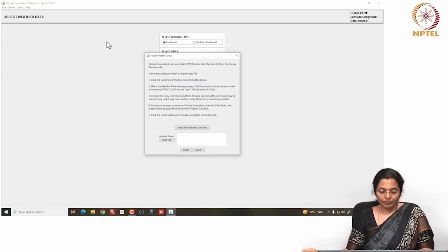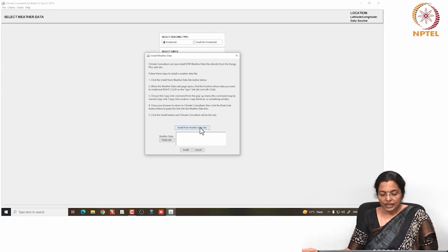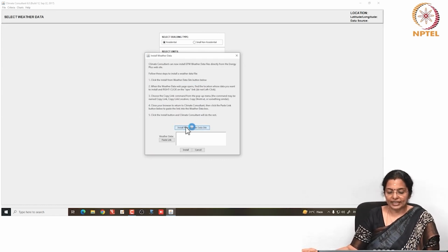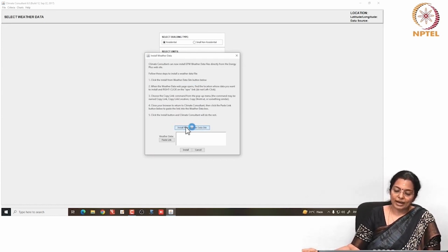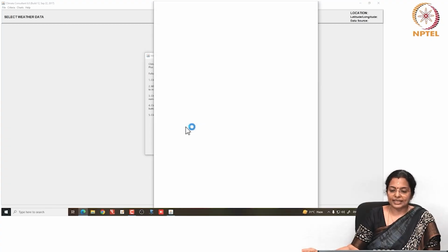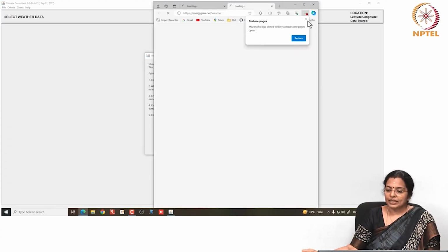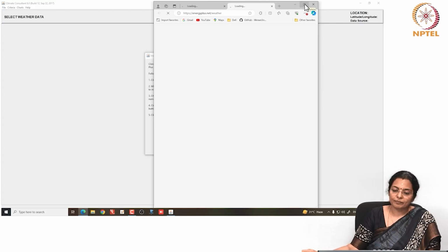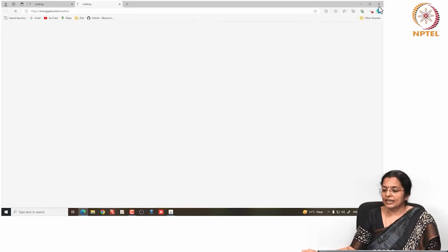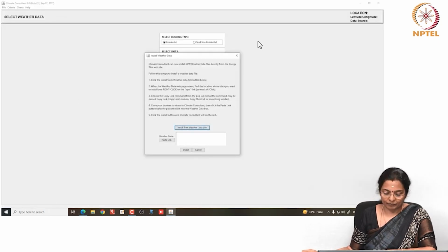Now, what I should do? I should go to install from weather data site. So, I will go to install from weather data site and it takes me directly to the energyplus.net weather station library. As it opens, I will be able to feed in the data that I require.